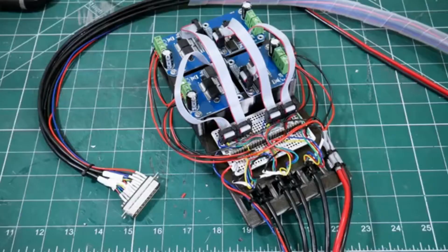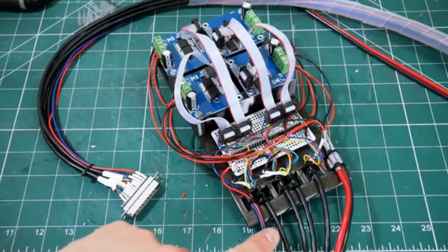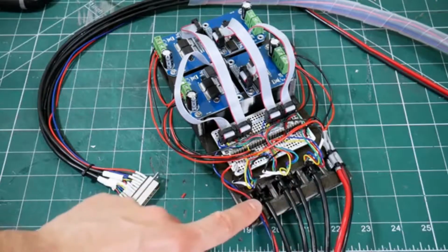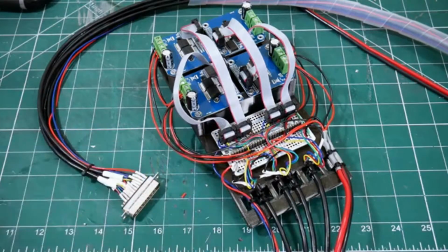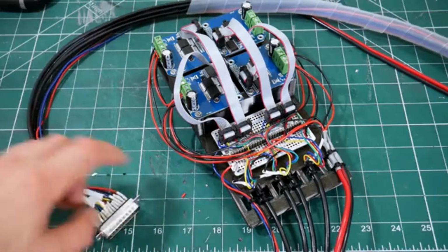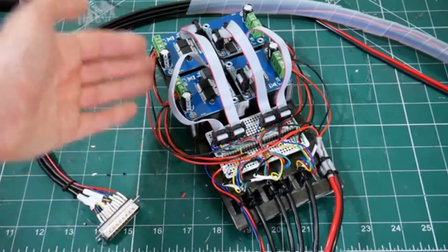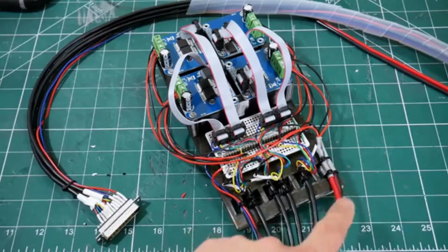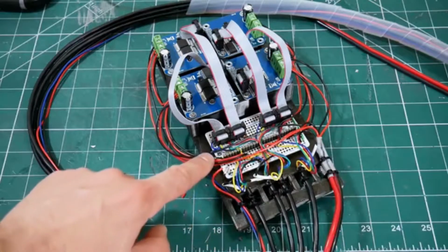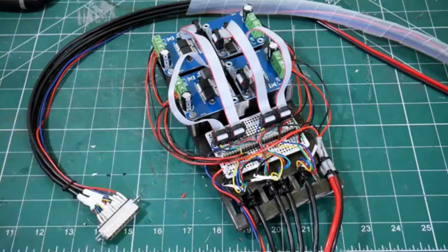Well, that's quite a lot worse looking now all of these wires are on. Obviously we've got these wires here that take the encoder signals and bring up the PWM signals for those motor drivers to drive the motors, and those all go to this connector that goes to our box with the Teensy in. So this wiring's a bit messy. We have got motor power coming from each of the motor drivers and going to the motor drivers from our main power wire. So ideally we'd make a custom PCB in the future with proper screw terminals, or PCB mounted XT60s or something.